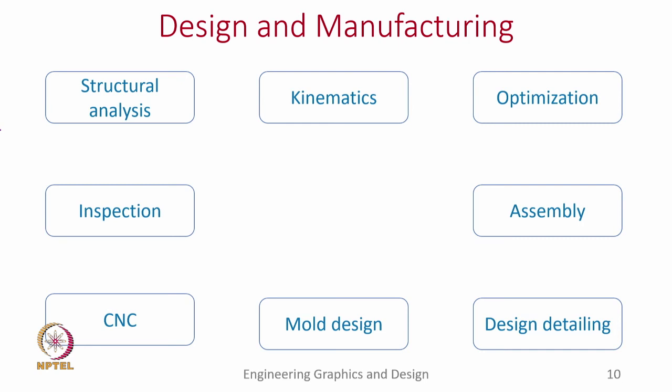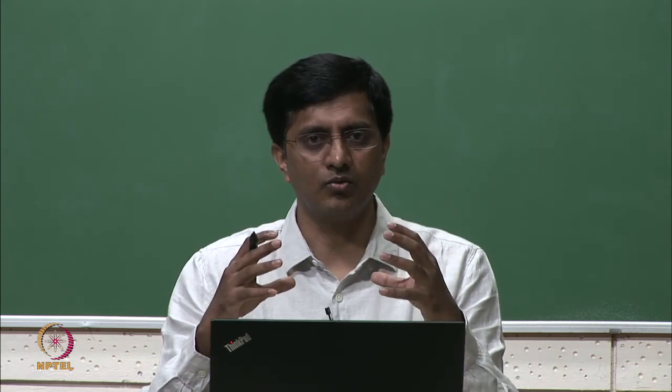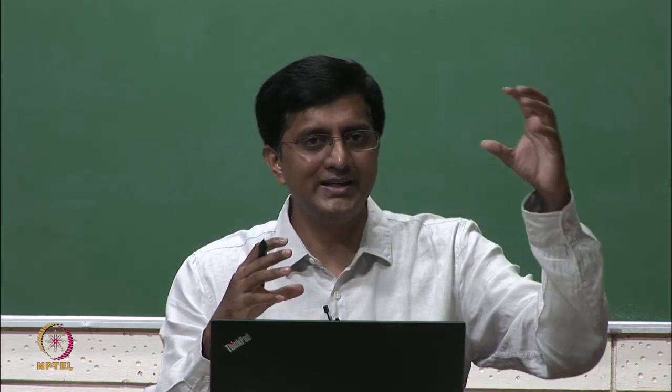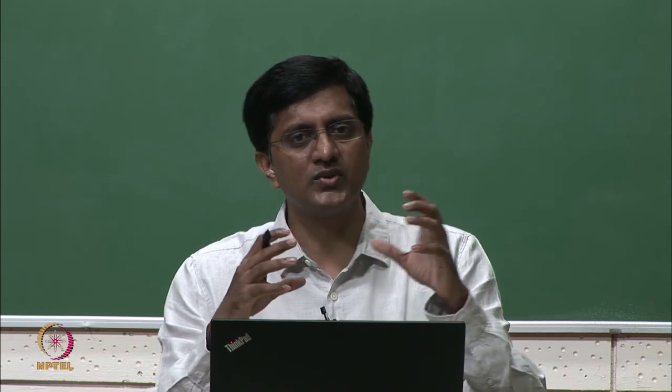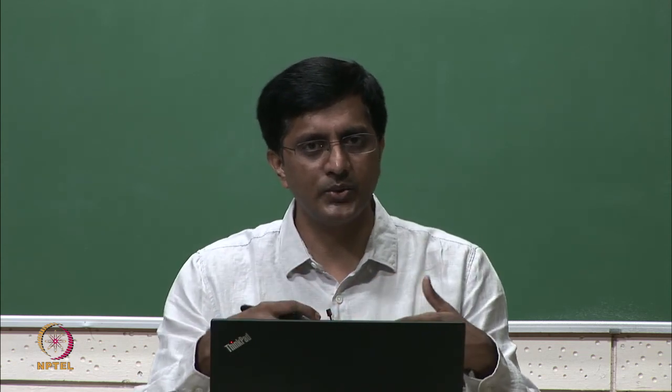Finally, let us say you have prepared the product and you want to inspect it before you send it to the market. Even for that you can use the CAD software, because you may have a laser scanner to scan the final product. The scanner will collect all the data points and recreate the model. Once you recreate the model, you can compare it with the initial design and see whether it matches the dimensions or the shape. If it is out of the acceptable tolerances, you may reject the component, and if it is within the allowable limits, you accept the component for going to the market.